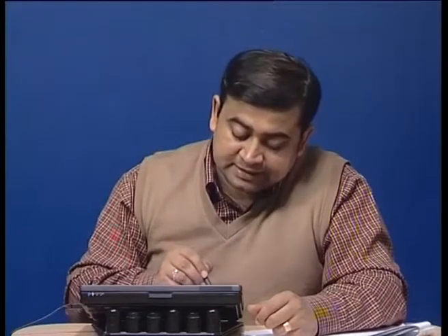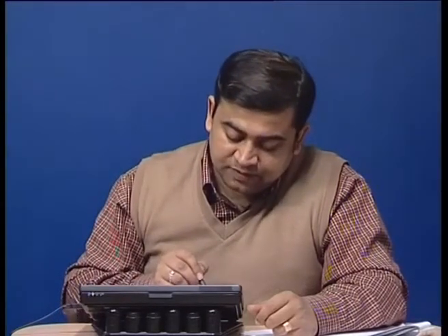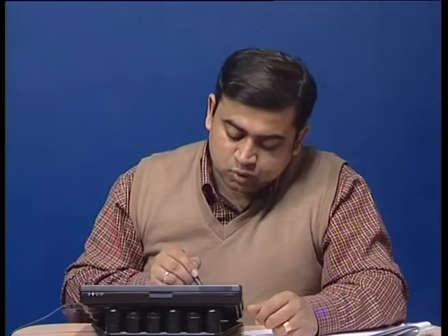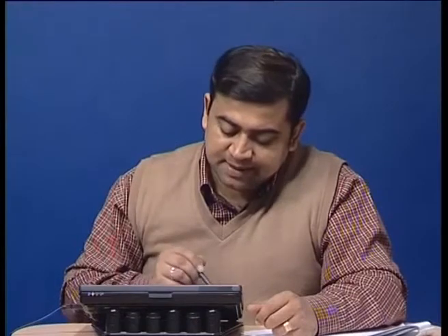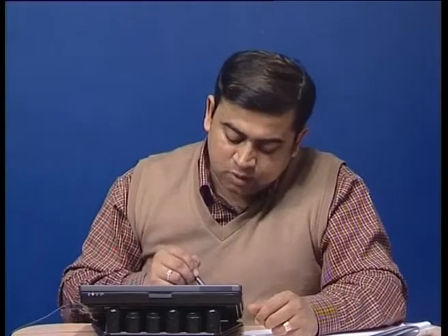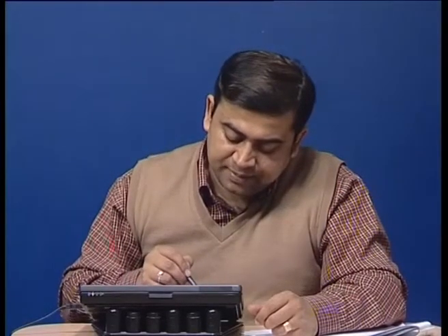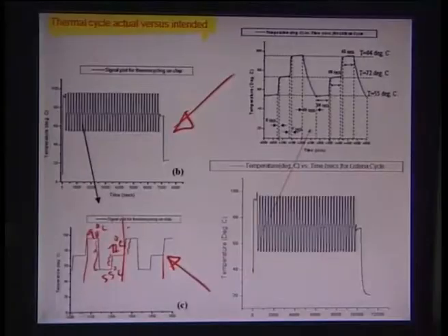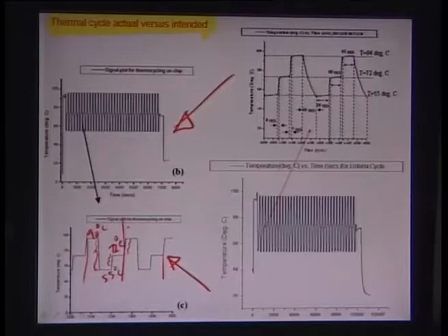So this essentially is the 90-degree step. This is about 55 degrees, and this is about the 72 degrees Celsius step, and you repeat this every time. In the process, you have to ramp the temperature down in this region and ramp it up in these regions. So you have to have proper thermal management for getting a better, essentially a lesser, cycling time.